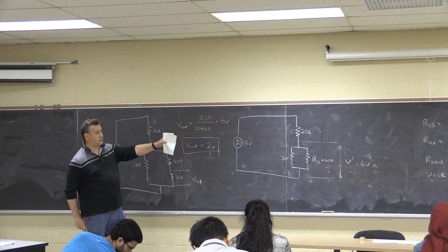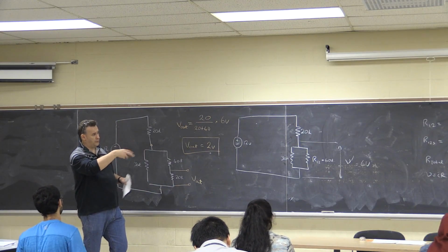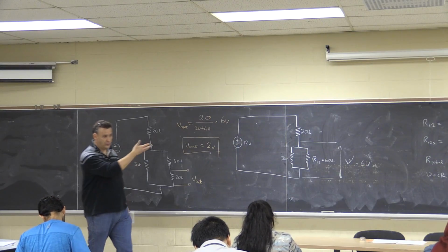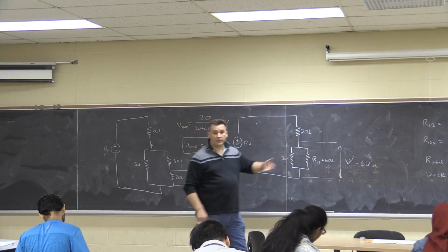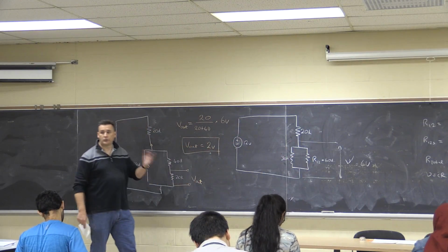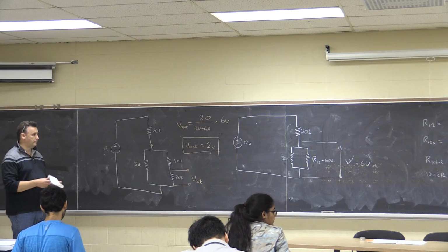Now you could work out the current, and you could work through the circuit, and at each stage you could work through currents and resistances and work out voltages, and I'll leave that for you to check, but you should end up with the same result at the end of the day. So current and voltage division rules can help simplify these circuits.